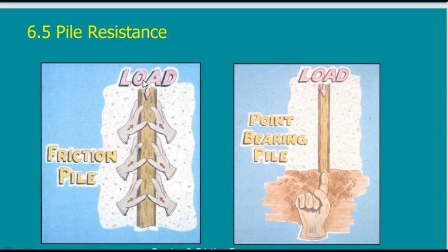Can anybody think what the difference would be if I have a pile subjected to 100 ton vertical compression and another pile subjected to 100 ton vertical tension? Is it the same? Will the reaction of the soil be the same? Why? What is the main item that will be affected? Yes, but for the friction, if I'm carrying this bag and the bag wants to slip down, or somebody wants to grab it up, if I'm holding it very tight, nobody will take it, either up or down. So for friction, it does not matter what the direction is.